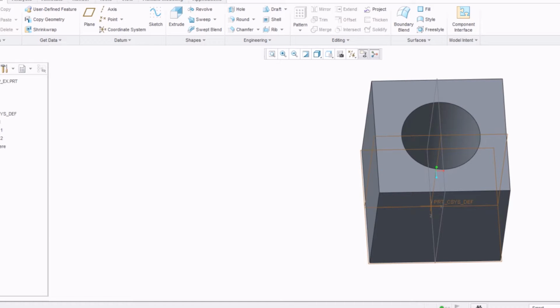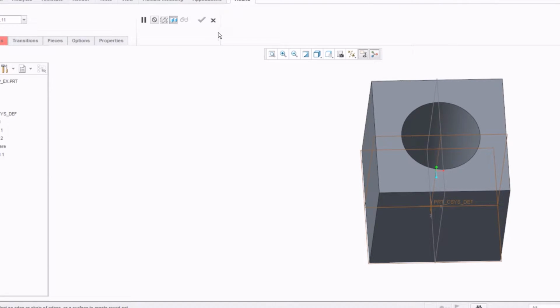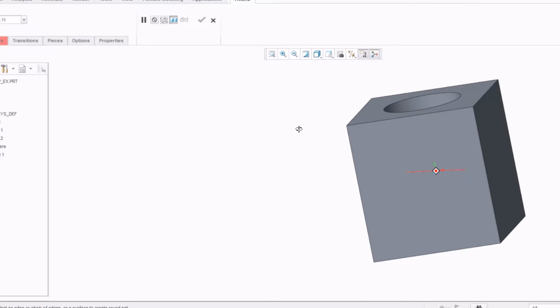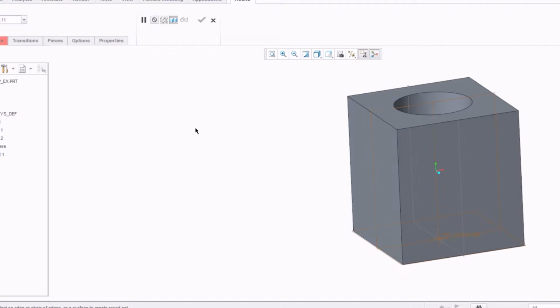Okay, let me close the browser there so that doesn't come up. Okay, so we'll go ahead and put the two options on there. First, we'll start with the round. So if we come up to the left, we see round. Click round once, and it will be prompting us for sets. Basically, it's asking us for what edges we'd like to use.